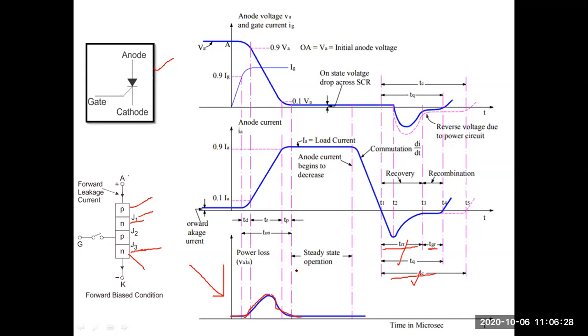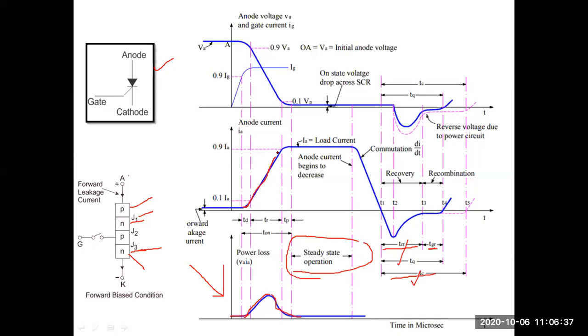This gives the steady state operation, that means the switch is completely closed here. The current slowly rises, and because of this we can see some amount of losses. We have to focus on the heat also, because when the temperature is higher, the switch behavior gets reduced because it deteriorates. So we need to provide heat sinks, or other cooling methods are also used for absorbing this heat. Or else the behavior of the switch gets deviated, because the behavior of these layers also changes.